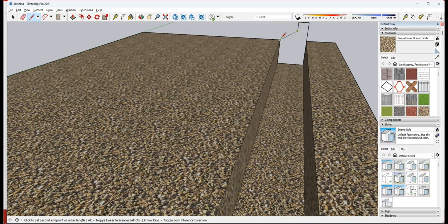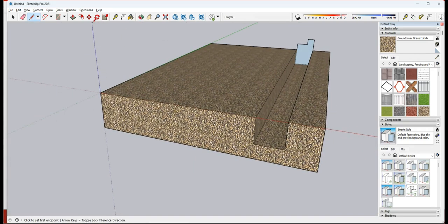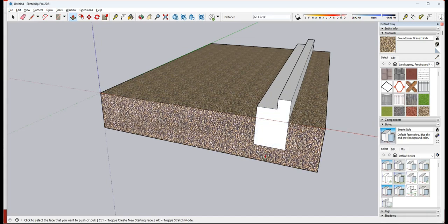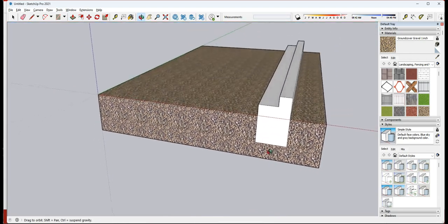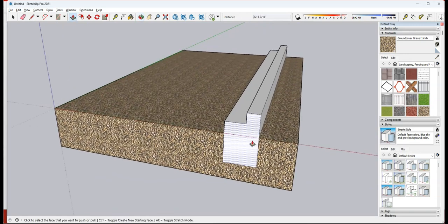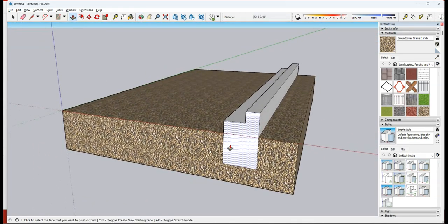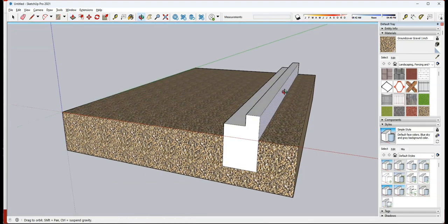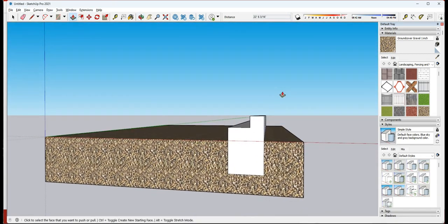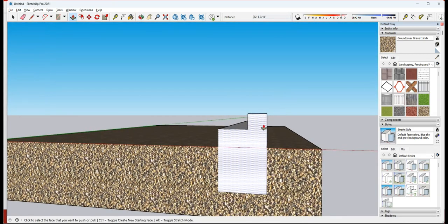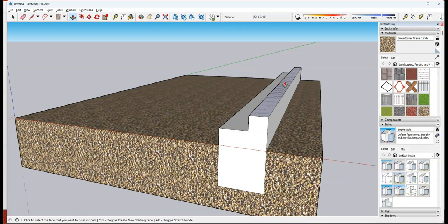Typically it would be like this, and that footing would be poured all across that ditch, which would be a strip footing running all across the length of the wall. And this little raised concrete here is where the wall framing would go.